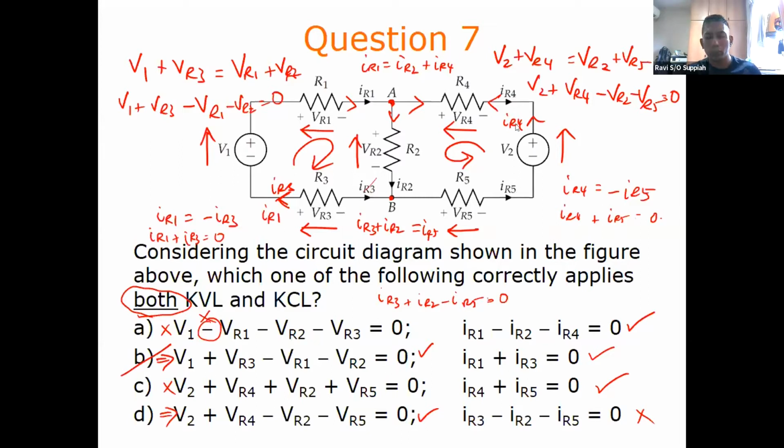That is perfectly fine, and that will only mean that the expression for node A will change. The idea is that for node analysis and the KVL, KCL approach, you are making some random assumptions. As long as the equations that you derive from these assumptions are valid and correct, then the rest of the analysis will be correct.